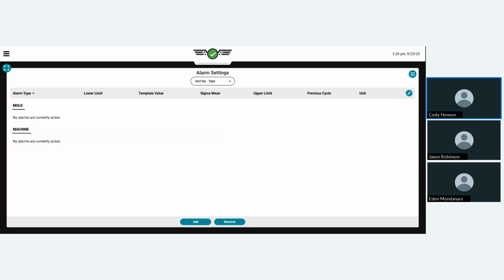And as we talk about alarms, right, it's important to think about the stability of our process. Similar to documenting the process, we do that when it's stable and when we've had a run in auto for a sustained amount of time, and alarms need to be thought of in the same way. Setting alarms around an unstable process will just have us chasing ourselves.